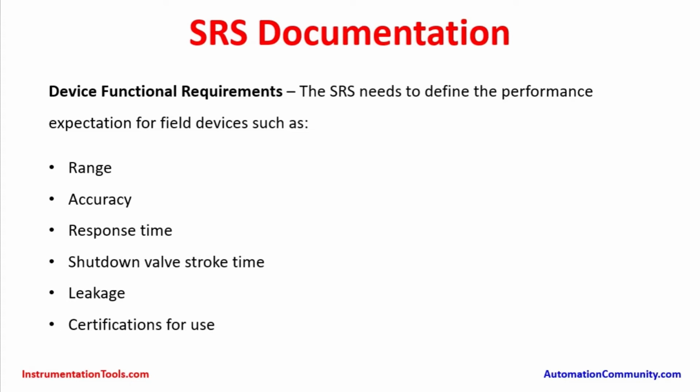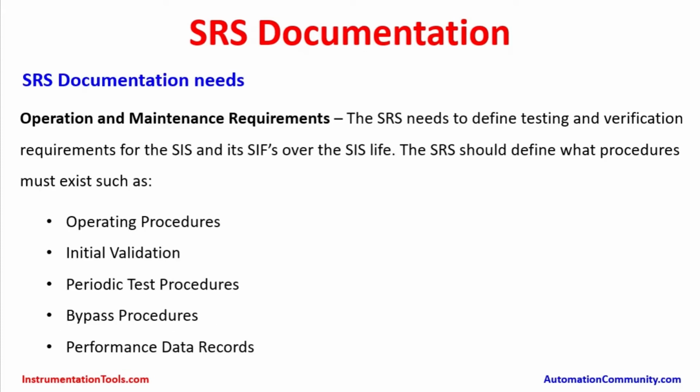There may be a requirement that the instruments and valves need to be certified to work in the safety instrumented system. Further we go on, operation and maintenance requirements. The SRS needs to define the testing and verification requirements for the SIS and its SIFs, safety instrumented functions, over the complete safety instrumented system life cycle.